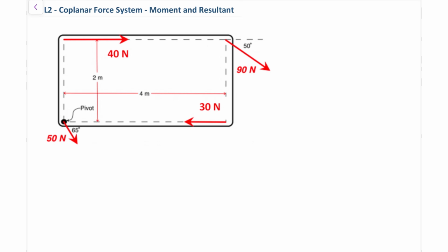So the first thing that you want to be able to do is to understand how to calculate force components. Force components is simply whenever we have a force at an angle, let's say a force like this one I'm drawing in purple, and I'll just do a dotted line to represent the origin for the reference. So here we have the force and the angle is right there at the center. Whenever we have an inclined force, we have to break that up into horizontal force components, which looks like this.